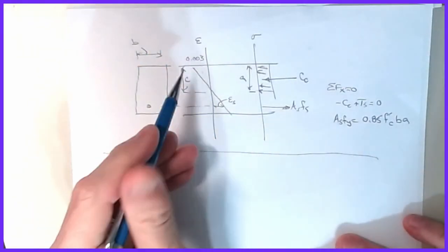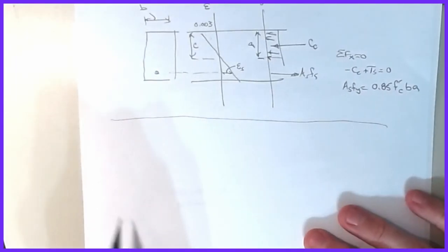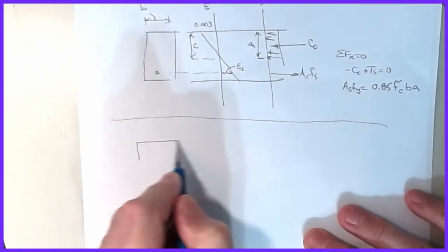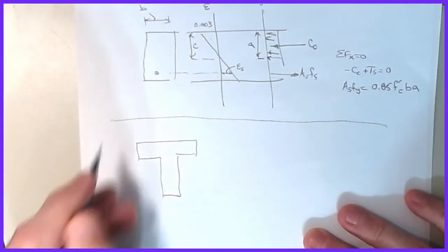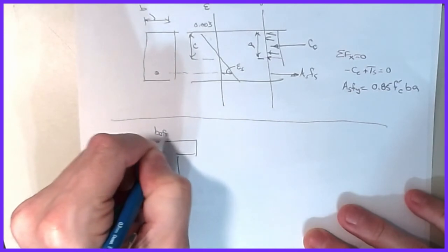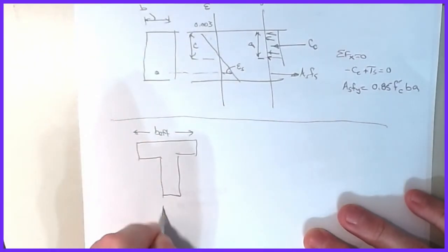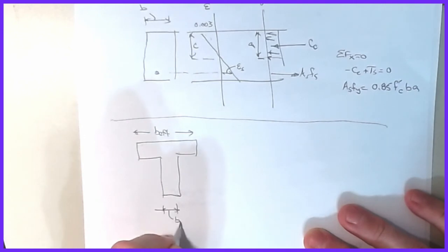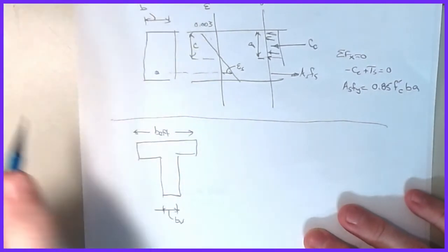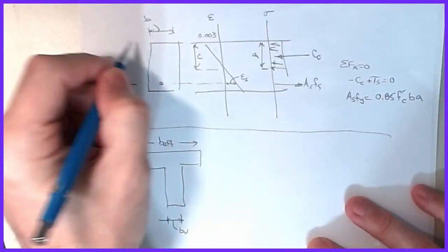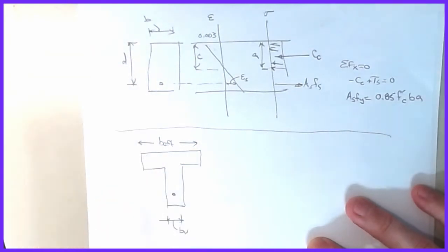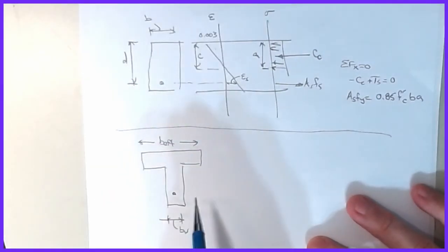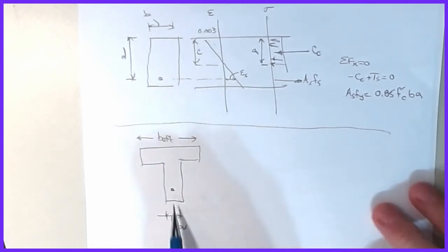Okay, remember you had to find c, but remember the method changed a little bit in beams when I started playing with something like this, where I had some effective flange width on here, and then this was my b on my web, and then you had all of your other dimensions associated with that. I left d off of this. Sorry about that. And so then you worked the process here. But do you remember the trick that was involved with the T-beam? There was one extra step that you had to do.